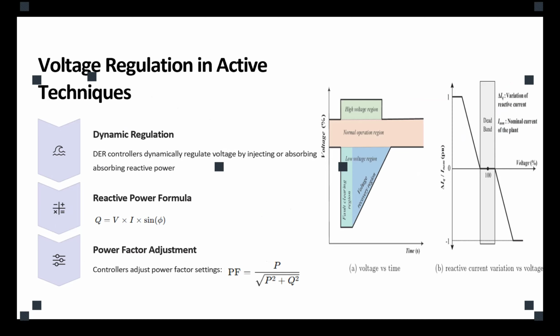Now, we always said there is a threshold. What's going to happen? There is a fault, the voltage is going to swell or sag. We have to compensate that. There is a threshold of the ideal situation. We want to define a threshold for more toleration, or fault ride through activity. But who defines those thresholds?